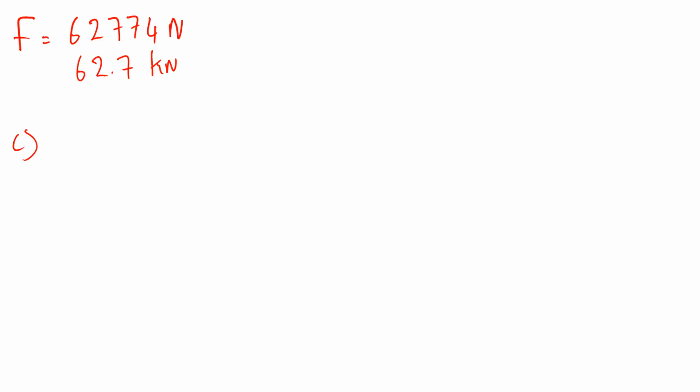However, hydrostatic pressure is mainly calculated for a fluid at rest. So you've got rho g h, but this time multiplied by area as well. So it would be half rho g h squared times B. So that gives you 1/2 times 1000 times 9.81 times H squared.